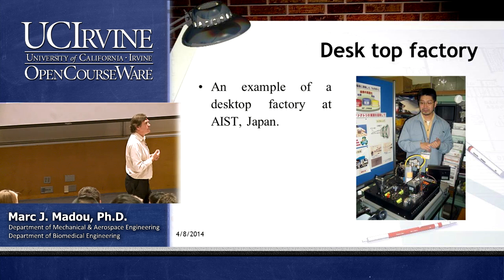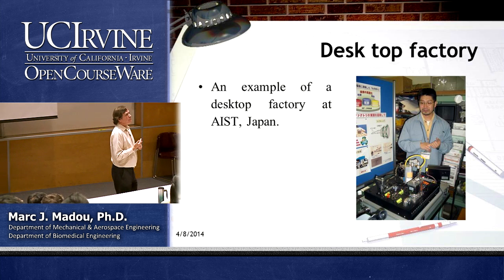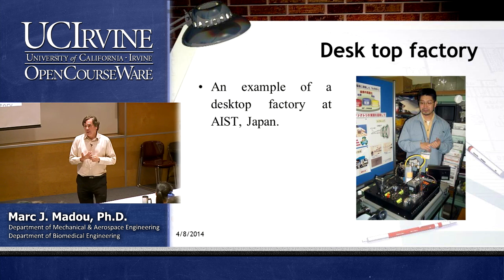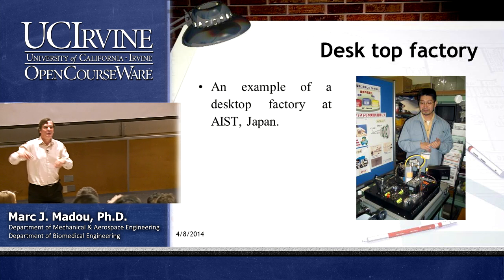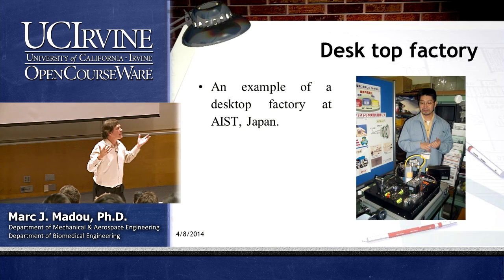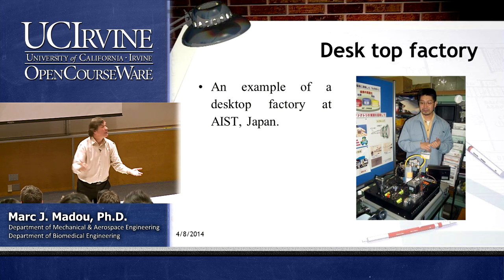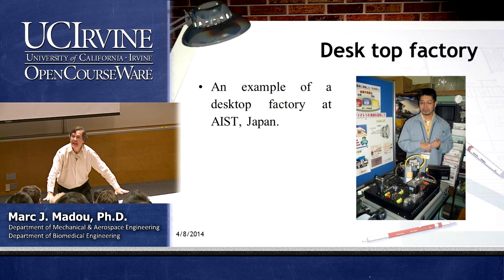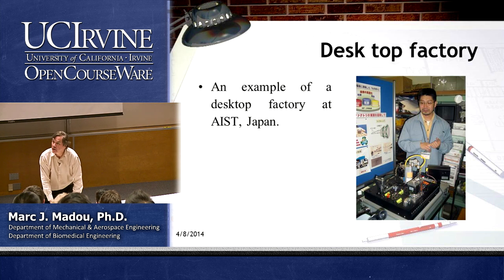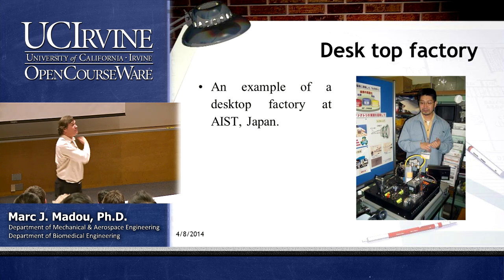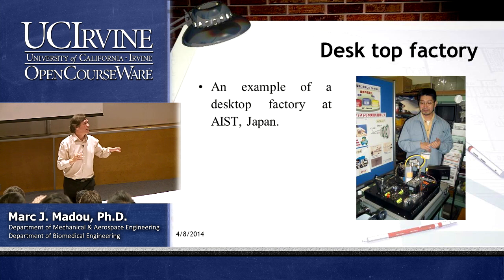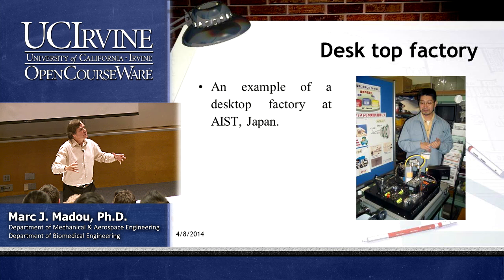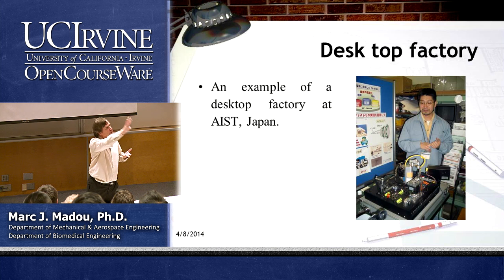Yes? What kind of things could you make with micromachining? Like, would you be able to machine channels for transistors or besides that? Okay, that's kind of interesting. I'm going to answer it with the proposal I'm just reviewing, right? Of course, I cannot give the name and the details, but people are now starting to think, look, the IC lithography, we will learn in a later class, is always planar, it's flat. You know, if you print transistors, it's on a silicon wafer, that's flat. With this machinery, you could actually put your transistors maybe on a cylinder, right? You could follow a shape. That's only one example. So you would have much, much more opportunity to print stuff on all types of surfaces.